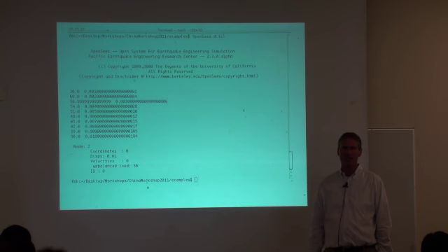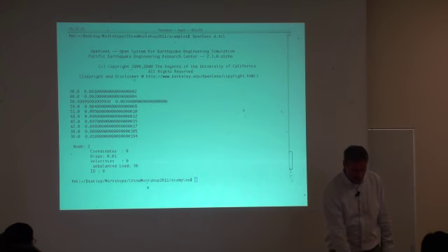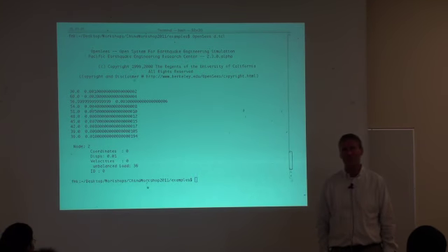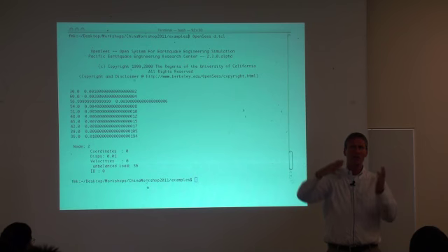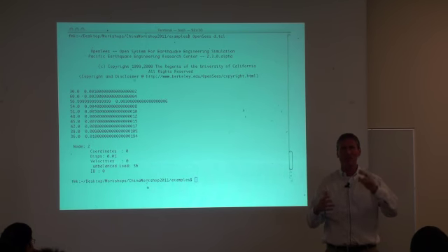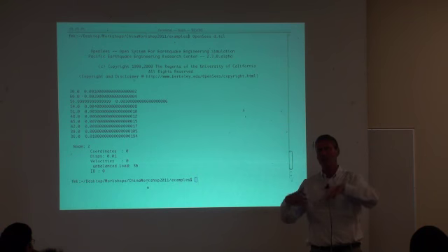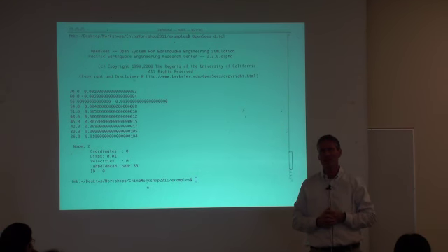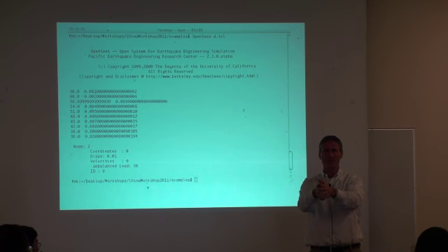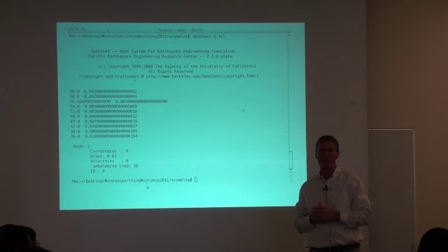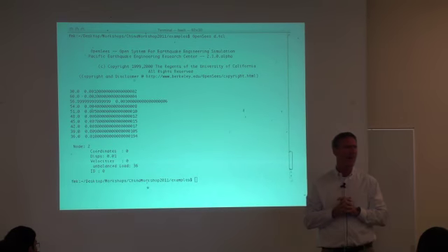Question: you use the command getTime. How exactly is time handled in the static analysis? Okay, the time in a static analysis, think of it as pseudo time. The time series needs a time to give me back the load factor. If you're doing a linear time series, it's basically the load factor. I'll get to it more this afternoon, what that pseudo time is in the static analysis, but think of it as a load factor. I'll delve into it this afternoon when I'm showing you what the different integration schemes are trying to do. If you are still confused, talk to me about it. Any other questions?